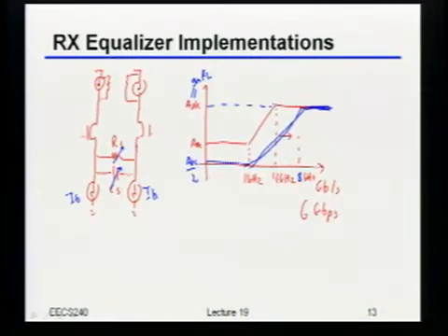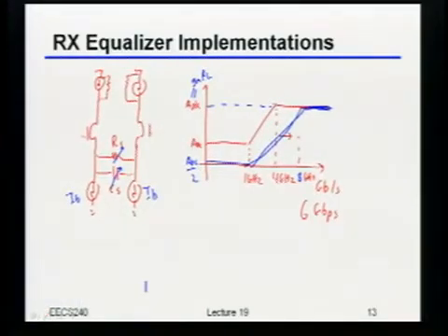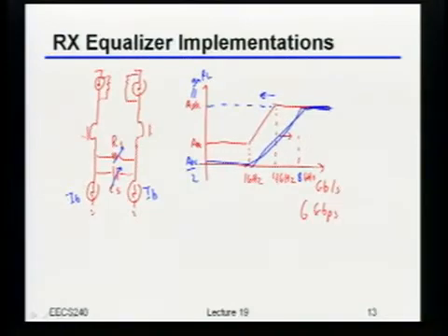Now, you're right, you can change the amount of power and rescale everything, but the point here is that this pole comes about because at high frequencies, the best you can do is make this a short. If you set that too high, you're going to be throwing away DC gain. Similarly, you'd say, okay, then maybe what I really want to do, I'll use a different pen here, is put the pole at a lower frequency, because then I could get higher DC gain, right? Okay, so now why don't I want to do that?